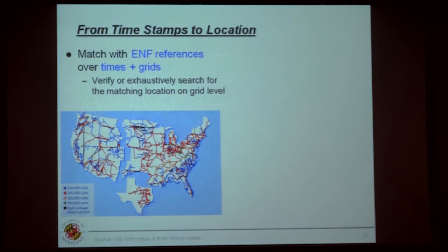Okay, so far we have seen the basic extraction of ENF from our sound signal and from our visual signal, and comparison with the ENF we obtain from our power references. We can use this for time stamping. The time stamping also gives us the capability to detect potential tampering if we see discontinuity, and to bind the different sequences together. Now, from when to where, I haven't answered: can we verify the location? The location question is actually quite interesting.